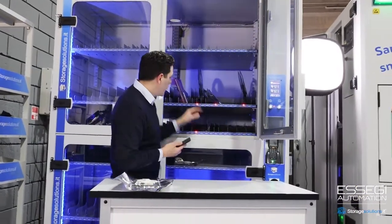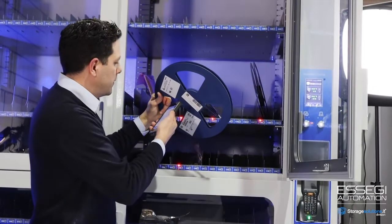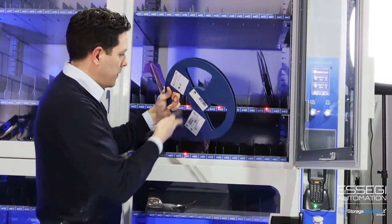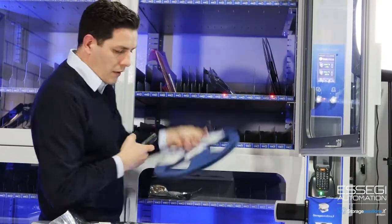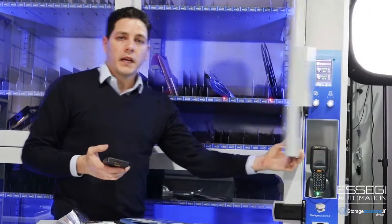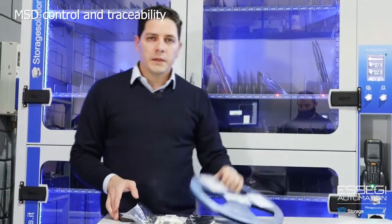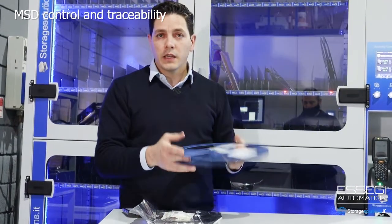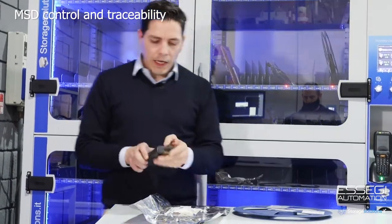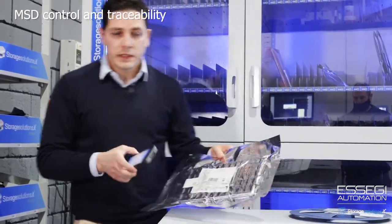It's very easy. The operator comes to the positions which is turned on and scans the material. Scans the unique ID. The light turns off, so I know that this is the material I need. All our equipment are equipped with humidity control. So if this was an MSD component, when I start counting when it comes out, I start counting the floor life. The PDA also allows us to keep track of MSD with the components inside a bag.